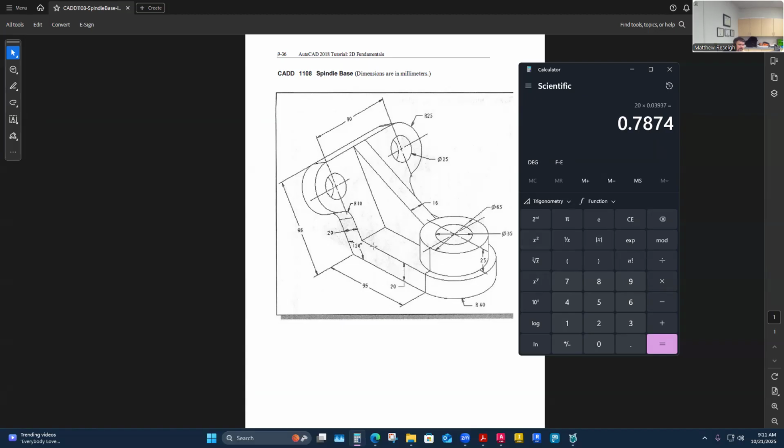When you bend really thick material, it doesn't bend at a nice sharp corner like is shown in this picture. It will actually have a big radius to it, and it would stretch the material strangely, and all equipment can be different in how it stretches material. So people who do that have to know their equipment and match the dies and the punches to the material thicknesses.